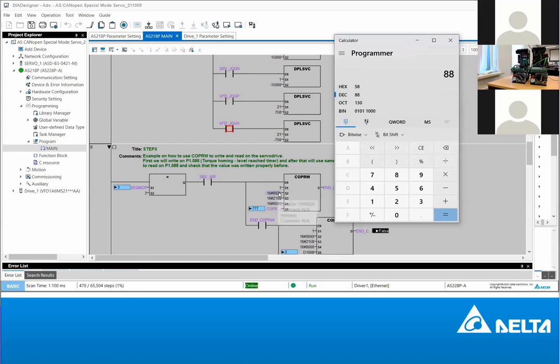So with this API, what am I doing? I'm using 2B. Like you saw, 2B is 2 bytes. This H2B, this is the request code. It's like the function code. 2B, I want to write 2 bytes to this index, to this parameter. And then this is the sub-index. This parameter is just one parameter. It doesn't have a sub-index, so this is always 0. If you use this API, it's always 0.